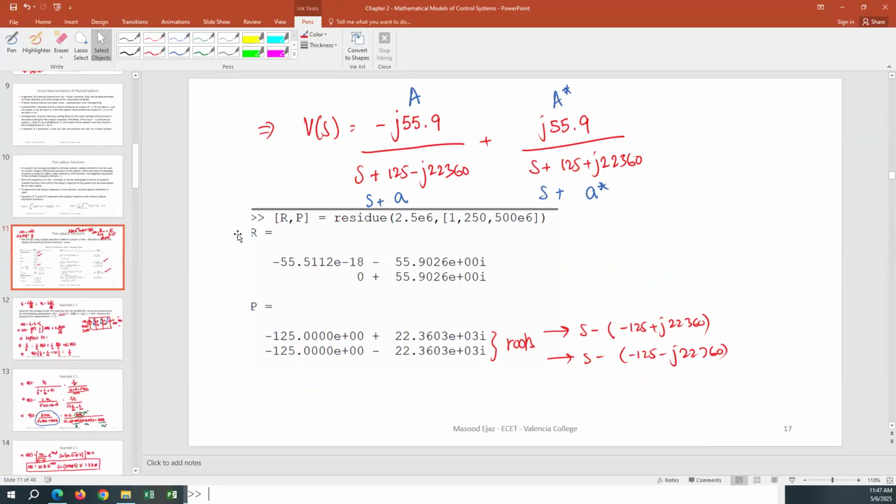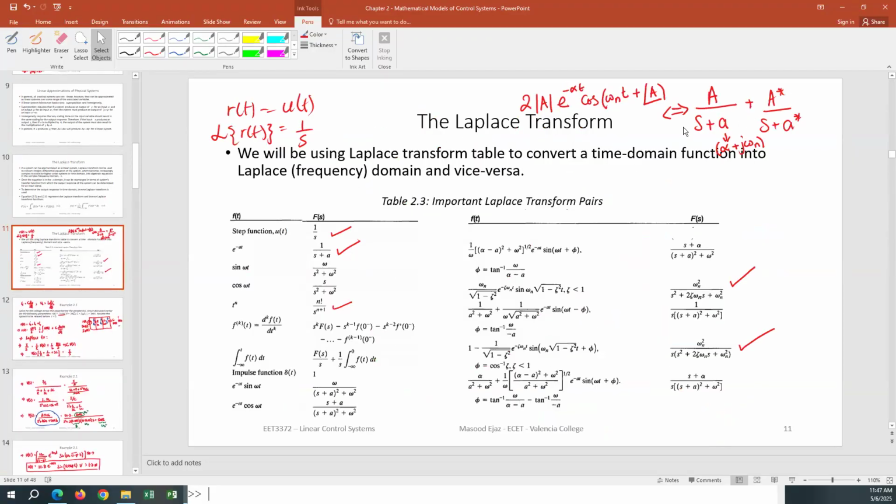So if we have this relationship, if we are getting this partial fraction decomposition, then instead of going through all that thing that I showed you, again, you should know that, but I'm not asking you to do the whole derivation. You can just apply this relationship and get the result. So let's add this over here. Again, this is the same thing as what we are having here, but that applies in any case, as long as your system is an underdamped system.